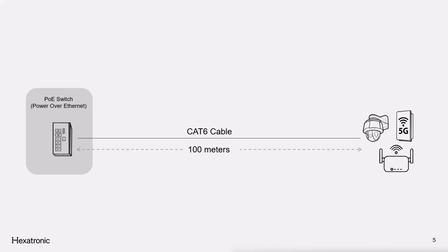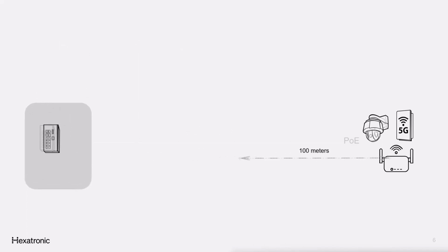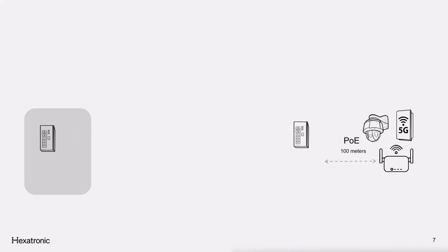So, what happens when your devices are positioned beyond this 100-meter boundary? In such scenarios, you need to relocate your industrial switch within 100 meters of the devices. Furthermore, to power the relocated switch, you must supply it with 230 volts AC power. AC power needs electrical panels, breakers, and a PSU to convert to the 48 volts DC required by the switch. For redundancy in case of power failures, a local UPS is needed. AC cables will require dedicated civil works, including trenches and ducts.